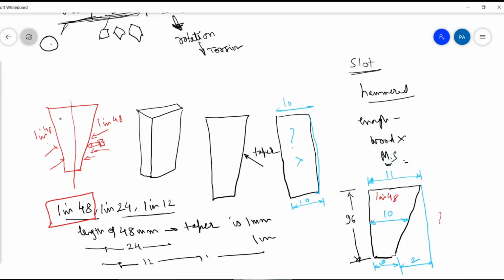Okay, you can see this is a corner, but actually this should not be a corner. This should be a rounded surface like this. Now here also it will not be a corner, it will be a rounded surface. It serves two purposes. The first purpose is it will not harm the operator who is using it, and second is it will reduce the stress concentration. There will be less stress concentration if it is like that. Already I have told you slightly about what stress concentration is in an earlier lecture. We will talk more on this stress concentration in the fourth module.